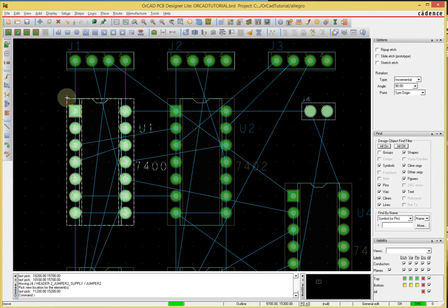Okay, and this is what this boundary, this shaded rectangle around my part, is supposed to signify: the approximate shape of the component. But based on the components you have chosen to use, you need to be aware of what the size of the component is, so that you can leave sufficient spacing around the component so that your component doesn't bump into another component when you put them on the board.